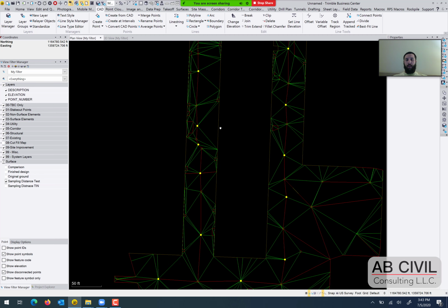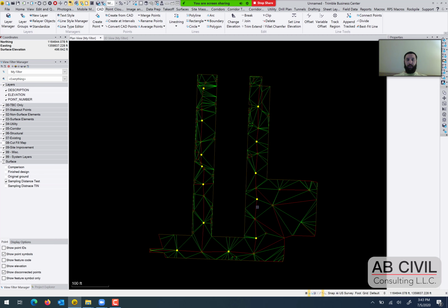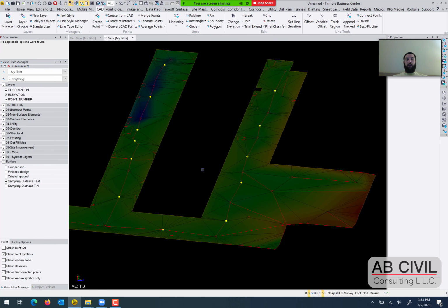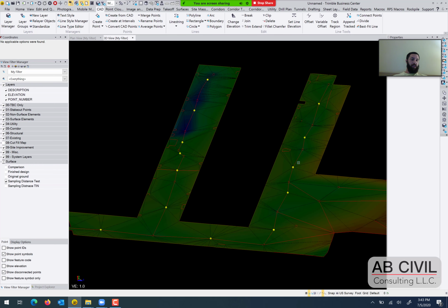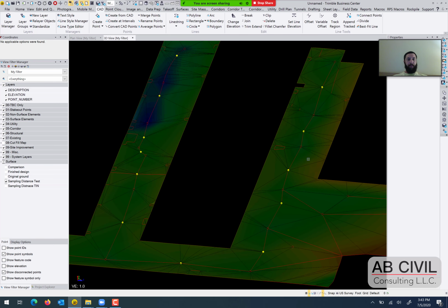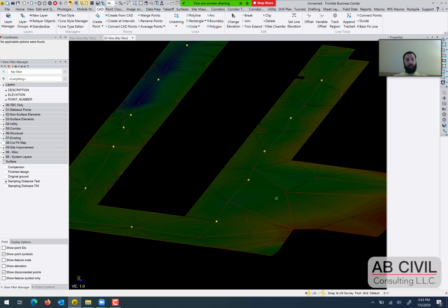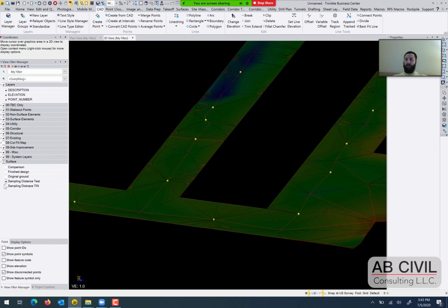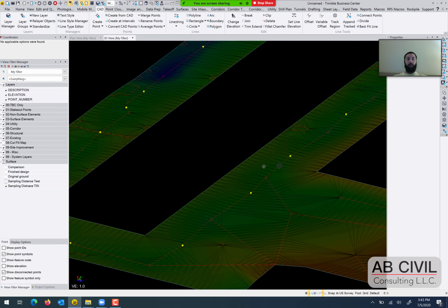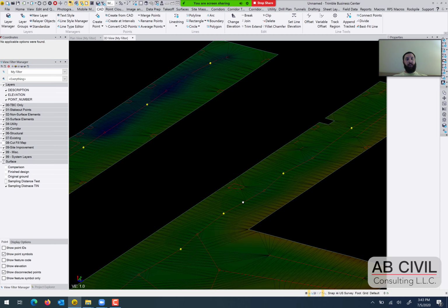But this model is not good if you see this. This is in 3D view with the elevation coloring added. You can still see that spiderweb effect of all these triangles that aren't really being computed like they should. If I turn on the better model, you can see every 5 feet it creates a triangle.